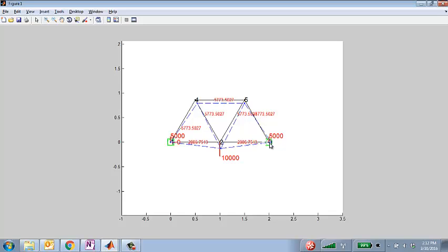It's only because the truss structure that we just did in the example was an indeterminate truss structure. That's why it caused internal forces in the other members. If it's a determinate truss, support settlement or some member getting extended or shortened does not cause any change. Okay.